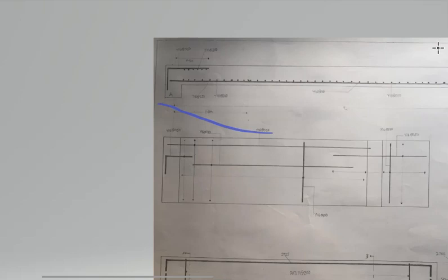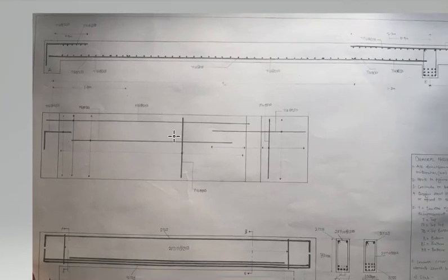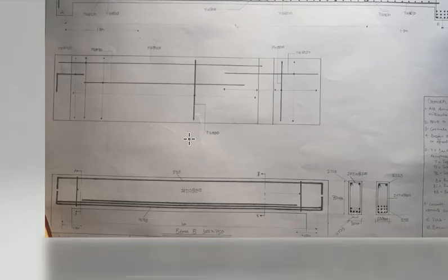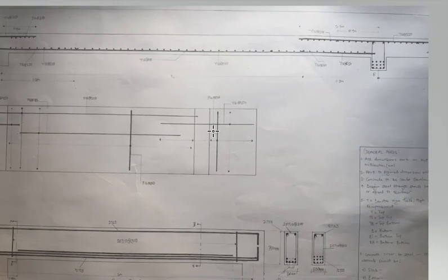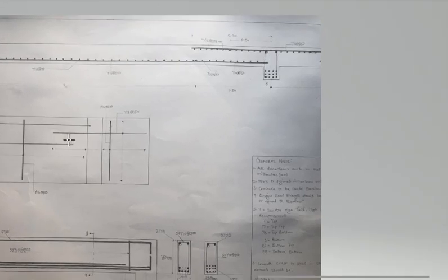That's why it's seen at 300, because of course again we don't want our bar spacing to exceed the maximum allowable, which is 300 mm according to the British Standard Code, as per BS 8110.